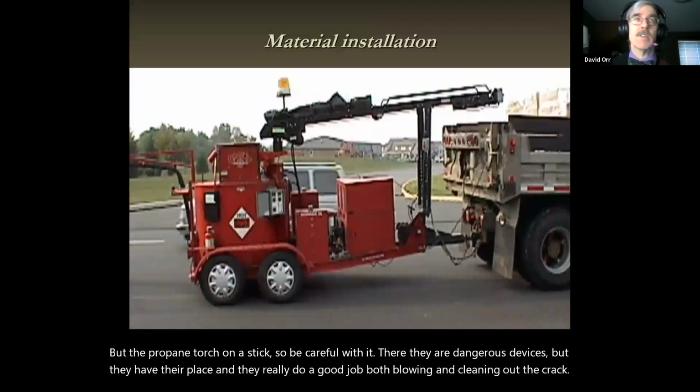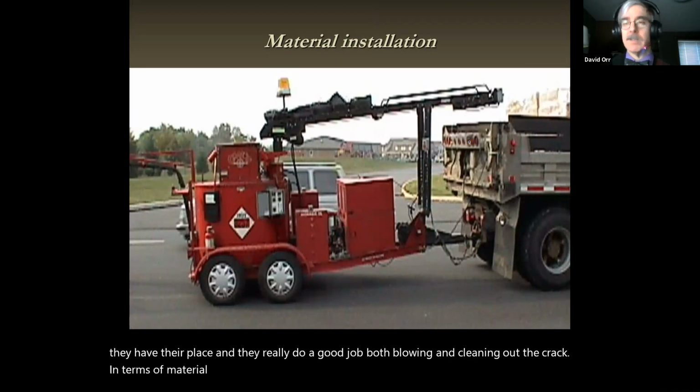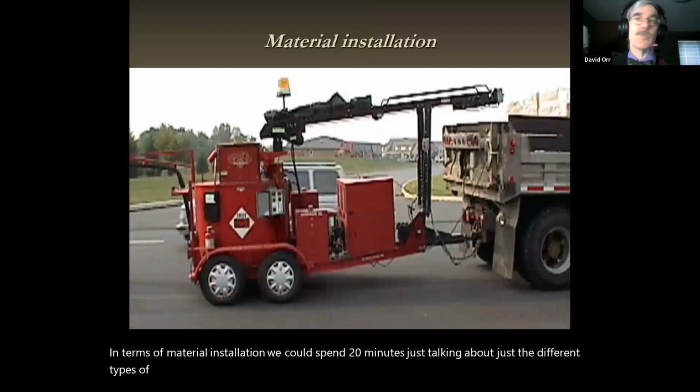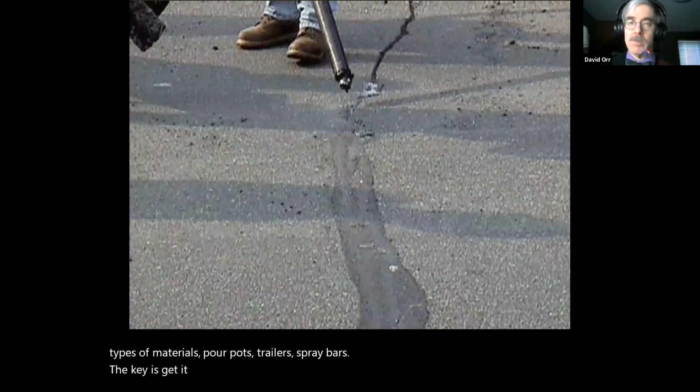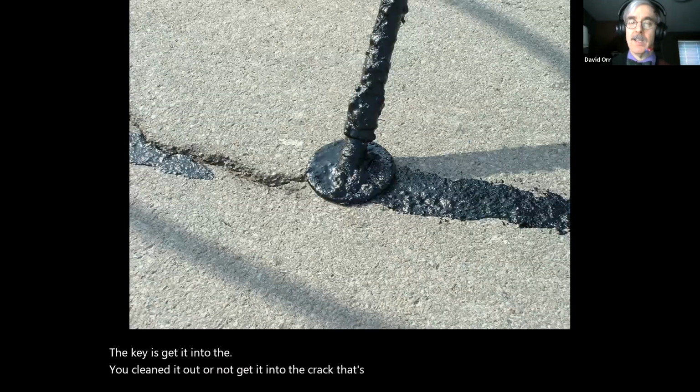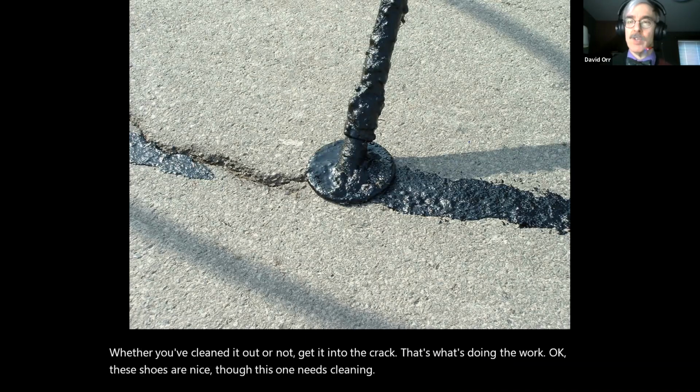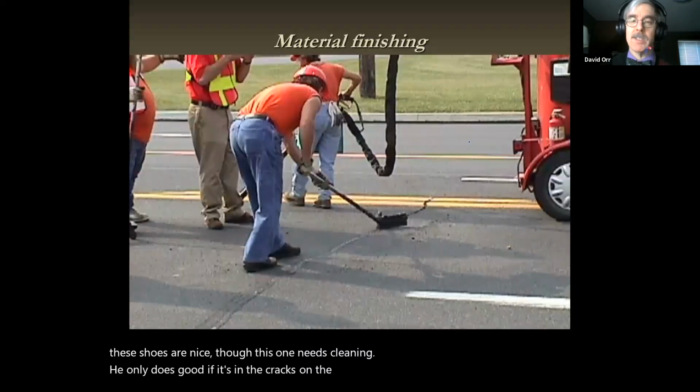In terms of material installation, we could spend 20 minutes just talking about the different types of materials, pour pots, trailers, spray bars. The key is get it into the crack. Whether you've cleaned it out or not, get it into the crack. That's what's doing the work, okay? It only does good if it's in the crack. If it's on the surface, it's not doing you that much good.